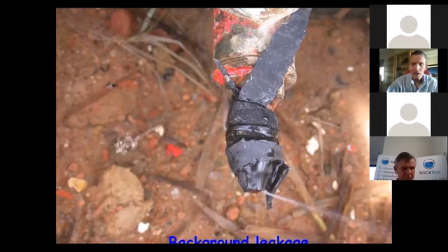And they developed an approach called the BABE approach, which stands for Burst and Background Estimate methodology. And it addresses leakage in the form of bursts, which are the big leaks that we've seen, and then background leaks, which are the sum of all the tiny leaks in the system.